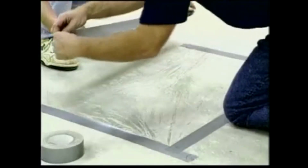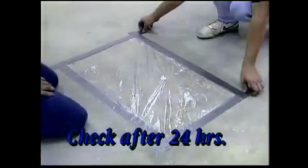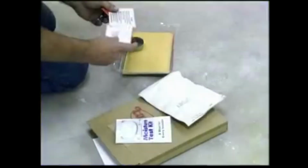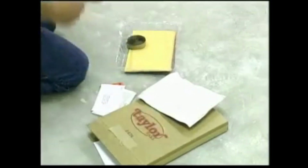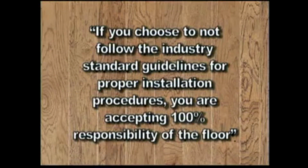The moisture content in concrete slab installations is especially critical to check. All concrete contains moisture, and the level is subject to change over time. The industry has standards for acceptable maximum and minimum moisture levels. Standard testing methods of moisture levels are required, along with documenting the results for future reference. If you choose not to follow the industry standard guidelines for proper installation procedures, you are accepting 100% responsibility of the floor.